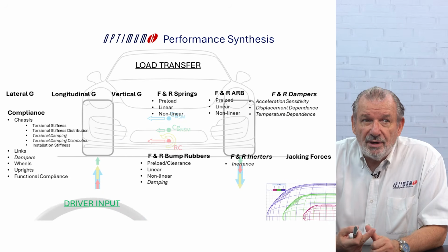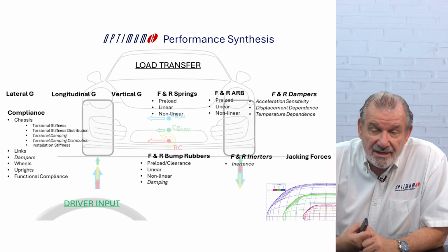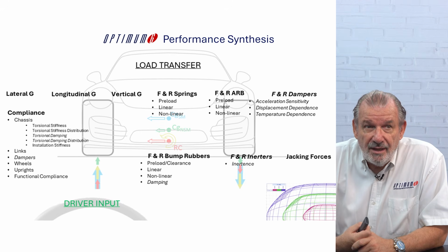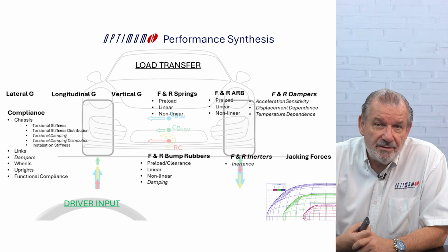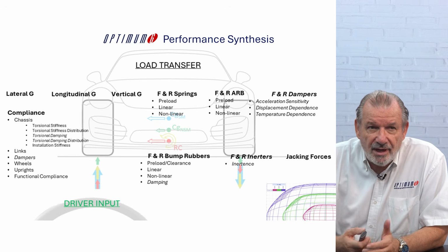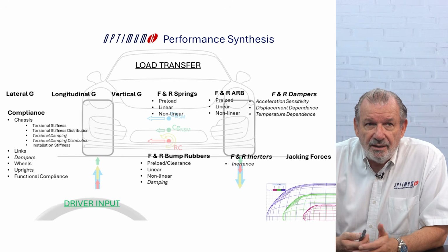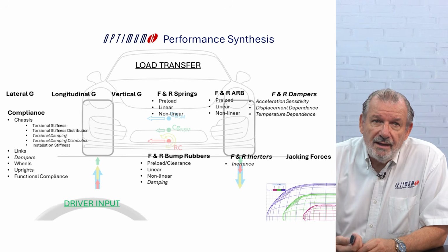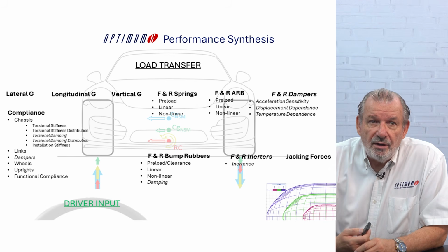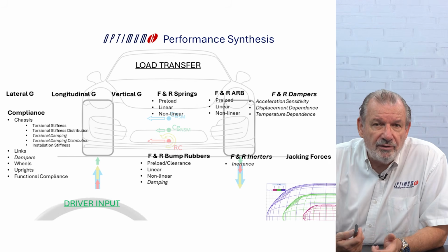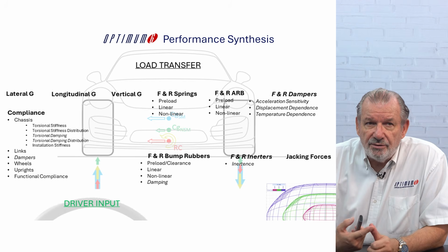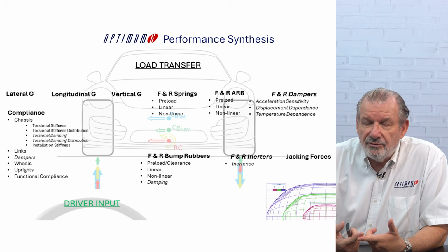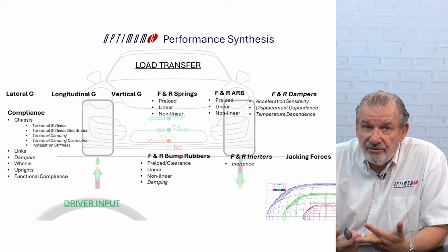So we speak about compliance. We speak about the damping, the chassis torsion damping, and all things like the rim, the camber compliance of the wheel, the rim, all the friction compliance, and then bump stop, whether you use bump stop or Belleville washers, for example, preload, clearance, linearity or non-linearity, and the bump stop itself is a damper.